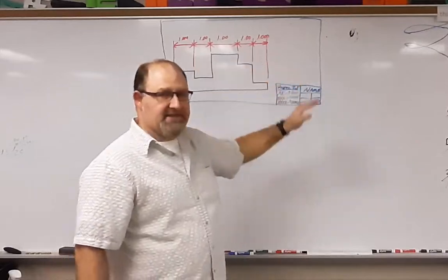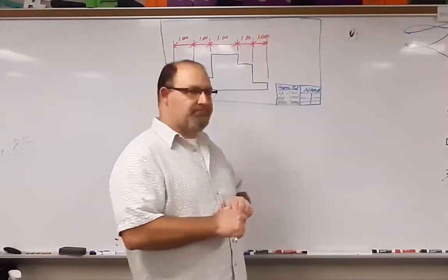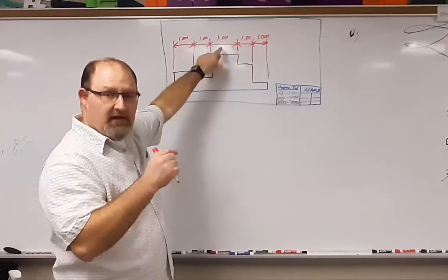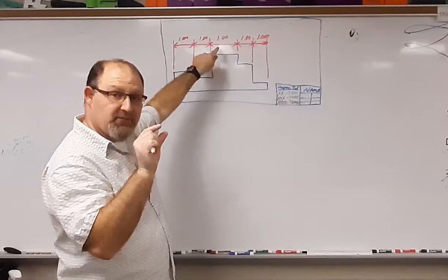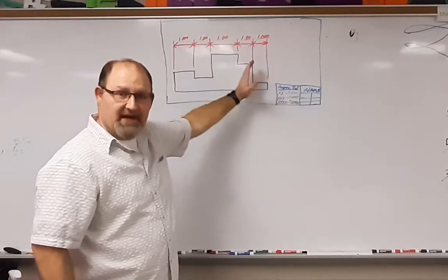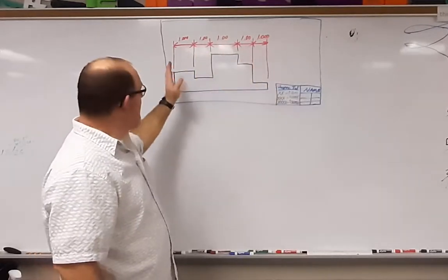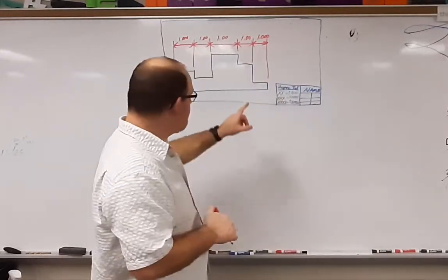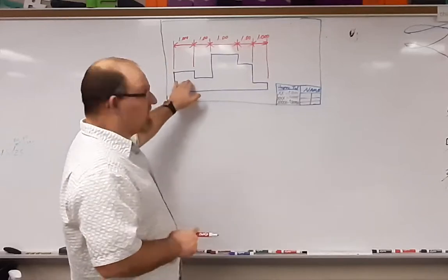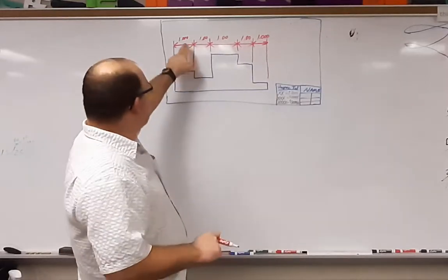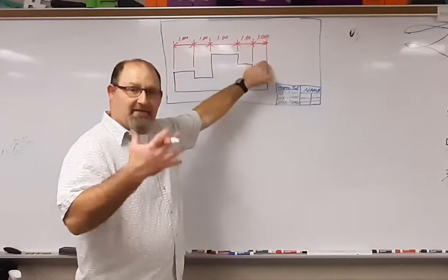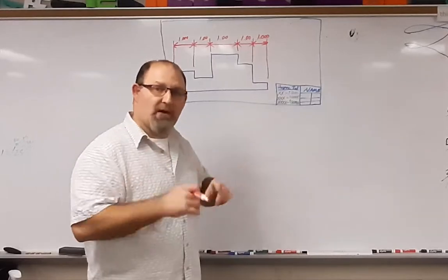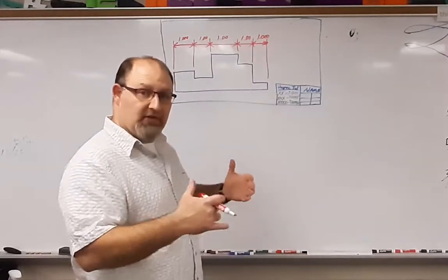So if we look at this method, this is called chain dimensioning. What we're looking at is how these dimensions will have this tolerance or this wiggle room, and when one is measured off the next, which is measured off the next, and so on, these tolerances will accumulate up really large or really small. So in this particular case, if we were to look at the overall size of this plate, so 1, 2, 3, 4, 5, it should be 5 inches long theoretically, but with the tolerances you have some wiggle room in there, so it may be a little bit longer, a little bit shorter.